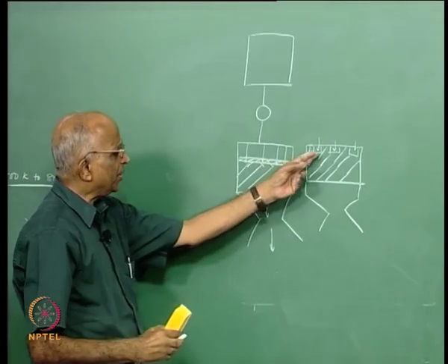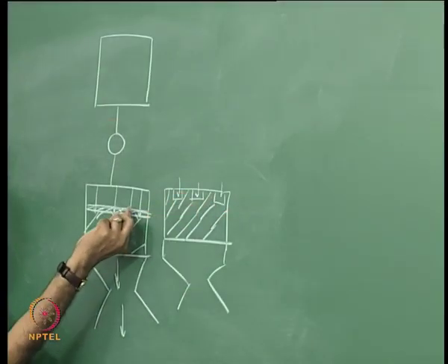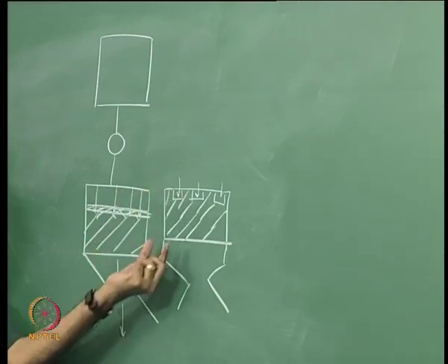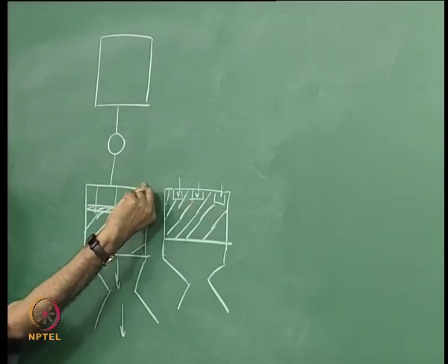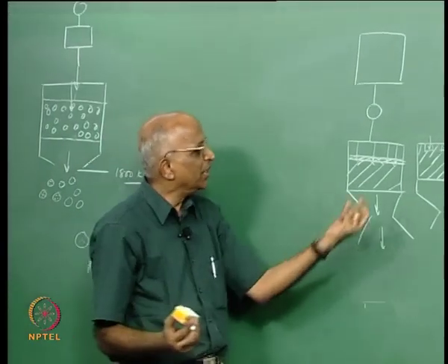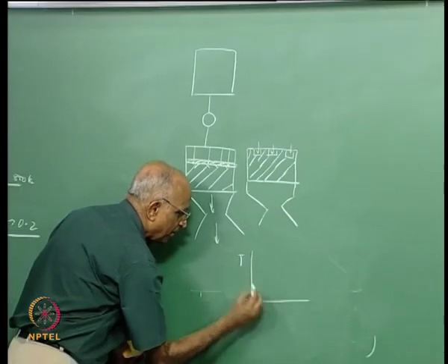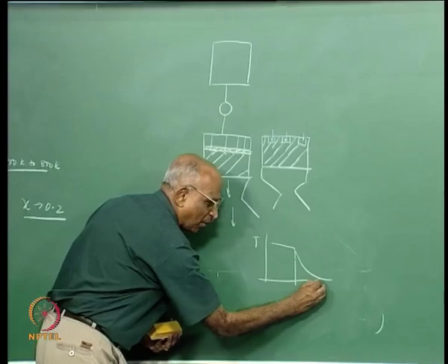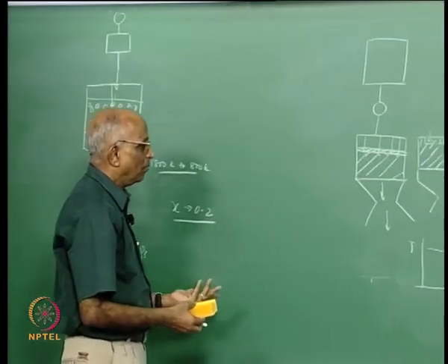It is of course necessary to make sure that whenever you put such injectors, could be some screens, could be shower head, could be these metal meshes over here, whatever we put, it is also important that the dribble volume, mind you, we talked in terms of manifold, must be small. If dribble volume is large, it keeps on dribbling and you will have thrust generation with respect to time. Instead of giving thrust like this, it may keep on going for a long time. That is the dribble volume.